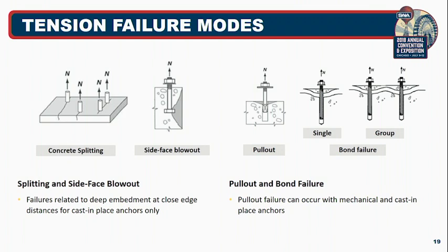Then you've got concrete splitting. This is typically applicable to displacement-controlled anchors and torque-controlled expansion anchor type systems, particularly when they're installed in thinner slabs, where splitting might occur. And once again, displacement-controlled anchors, what I'm talking about is like the shell anchors that are typically utilized in your industry for attaching scaffolding. And the torque-controlled anchors are like the wedge anchor systems that I'm addressing here.